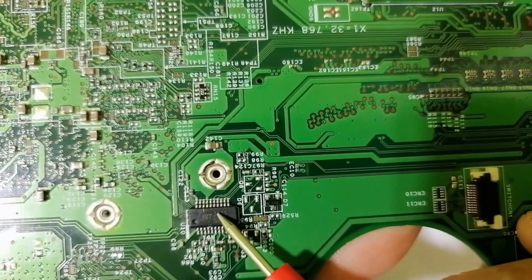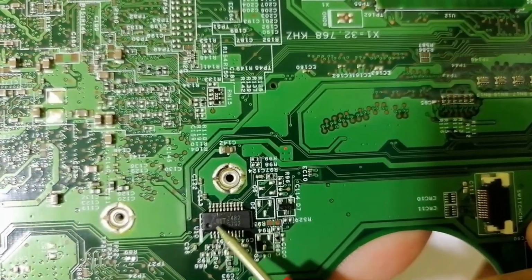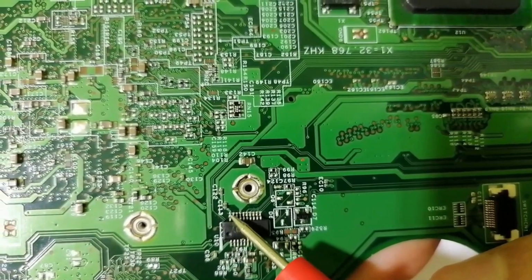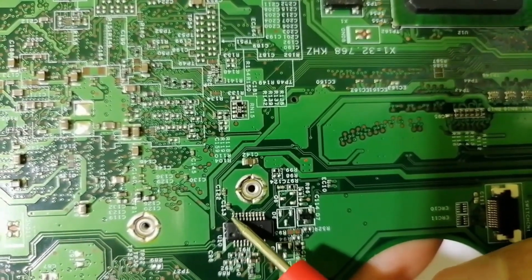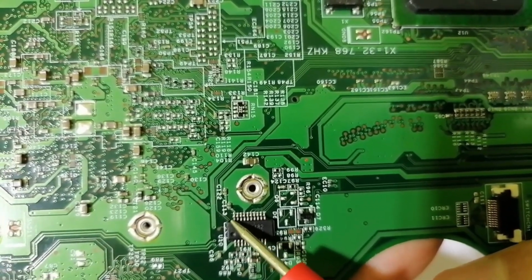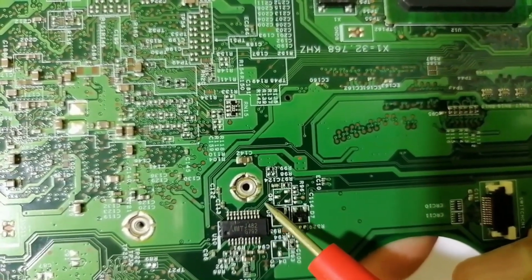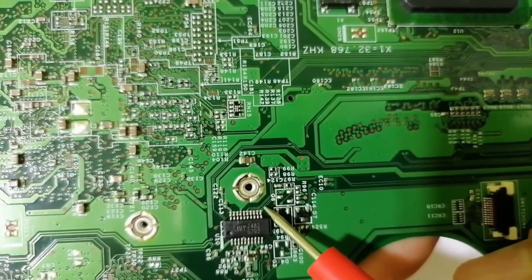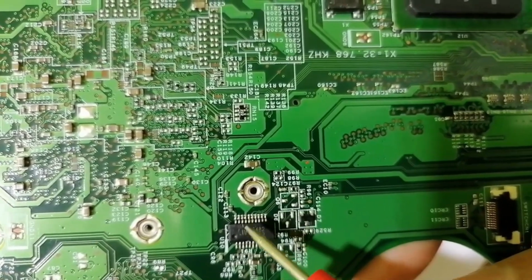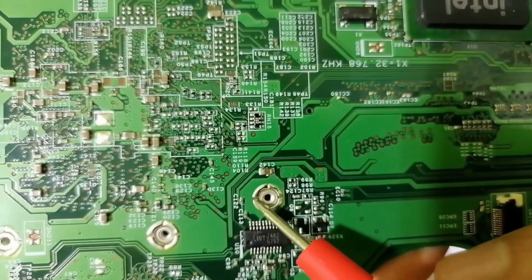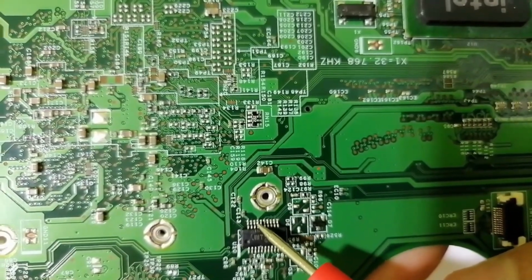We have another IC, a clear IC, as you can see. Guys, this is basically pin number 1. Do you see in this pin we have a bolded line, which means here it gets input voltage, the power in. And over here, do you see the signals? These are just enable signals and control signals. And over here we also have a bolded line connected to this hole, which means here we have ground.